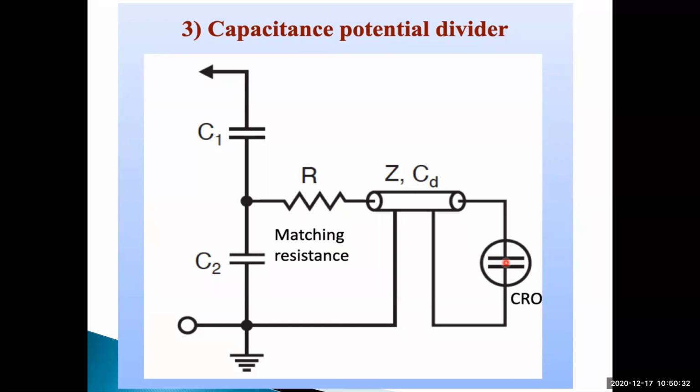By placing them, you observe the reflection and refraction of voltage waves and current waves. You already studied this in long transmission lines, with an open circuit at the end of the line, a short circuit at the end of the line, and also an impedance placed at the end.